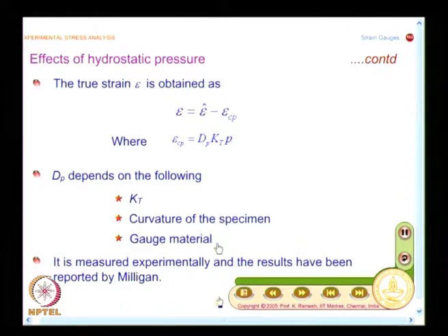See, when you go for finer measurements, the specimen properties matter, the foil alloy properties matter, and when you are looking for the changes because of the pressure introduced, these changes have to follow a predictable path when pressure is increased gradually. This demanded a very fine installation of the strain gauge on the specimen.